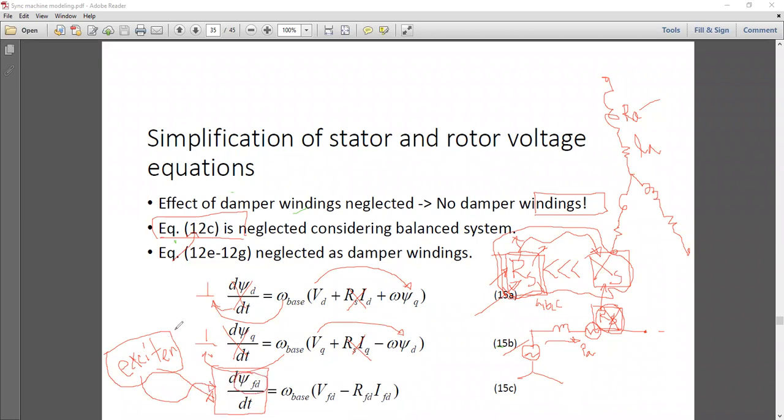If you don't include the excitation system, then you reach your swing equation model or classical model. With the inclusion of the excitation system dynamics, we have our third order model. This is our third dynamic equation along with the previous two. Remember what the previous two were?